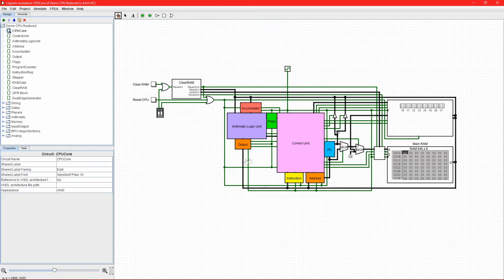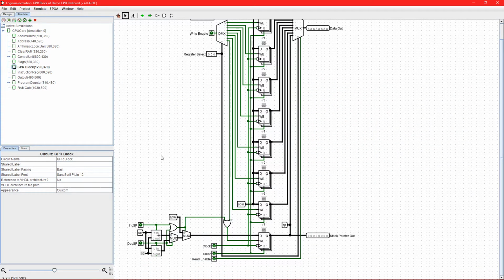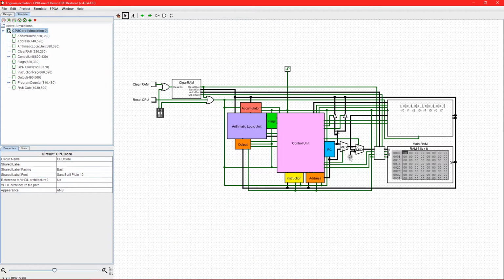So first, from right to left, if we scroll down here, we can see that we are using some special circuitry attached to register 7. Register 7 is now the lower half of the stack pointer. The upper half is right here, 08 hexadecimal. So you have 2 kilobytes for your program, followed by 256 bytes for the stack. And we also have a new signal to put the stack pointer onto the address bus.